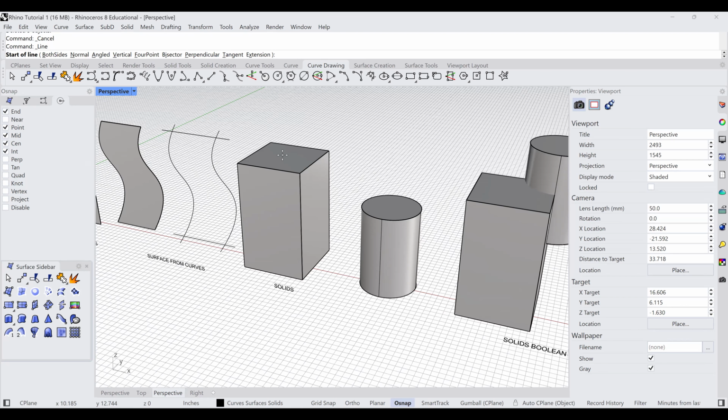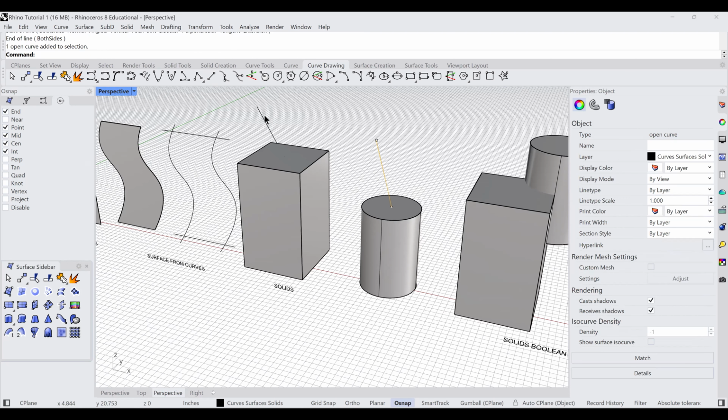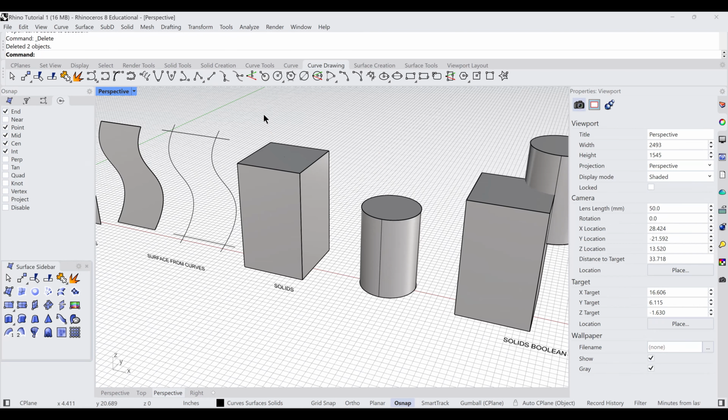Here you need to click the parameters, the outline of the part you want the center of. So if I click this end piece here, that white line comes up and there's a little white square in the middle. And I stay here and I click, it now is putting this line in the center of that square surface. Same thing would happen on any kind of hexagon, any kind of triangle, whatever you want. Same thing happens here with the circle. I'm clicking to the center of that circle by clicking on the parameters of that shape. So that's snapping to center.